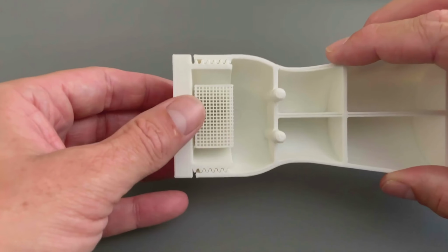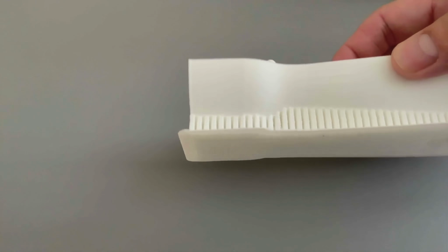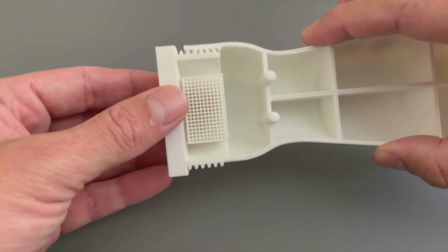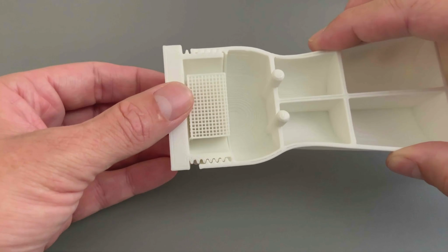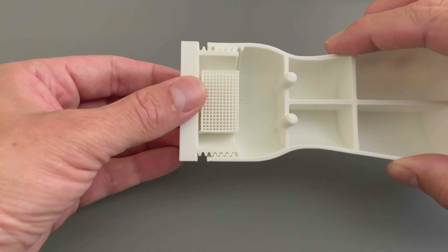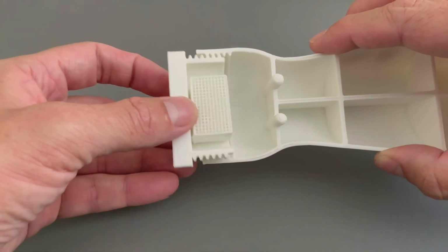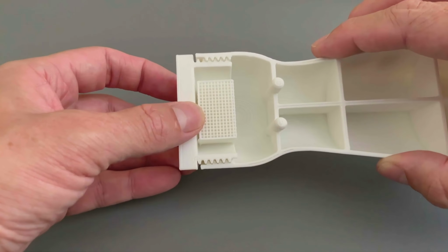If you want to do a mechanical test, here I have a shell which I printed with fine quality, and here I have my head with a fine quality, and I want to figure out if this really works. Then obviously I need to print those in a really good quality, so that when I prototype everything, it will work. So you see the layer height and also the nozzle width really influence the print quality and then the time.